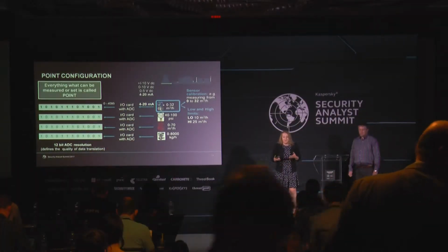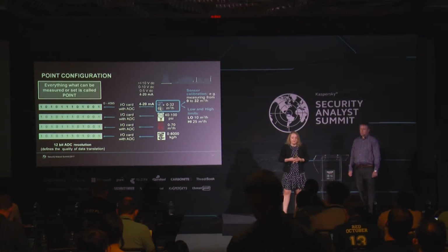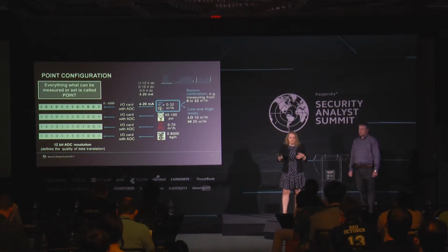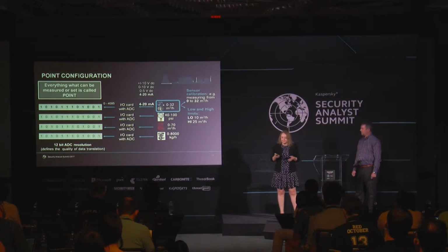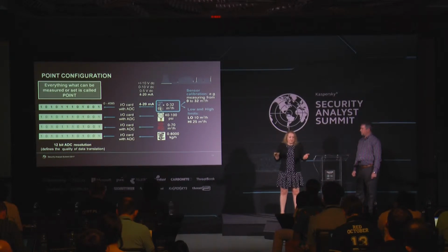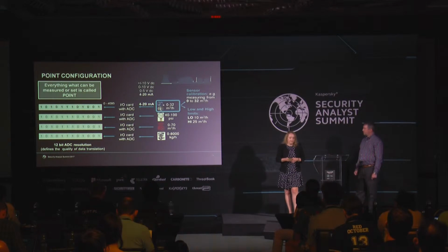So the electrical sensor signal will be scaled, basically transformed, into a proportional signal, for example a current signal from 4 to 20 mA, most typically used. And then it goes into the input-output card, and that will be mapped, basically converted by the analog-to-digital converters into a decimal number. Eventually that measurement will be presented as a decimal number, in our case 12-bit resolution from 0 to 4095.